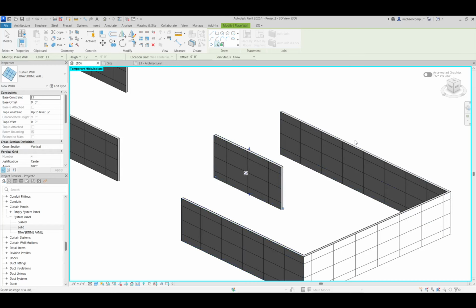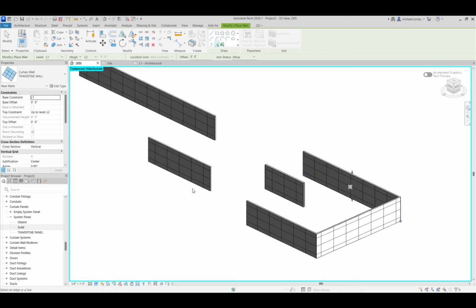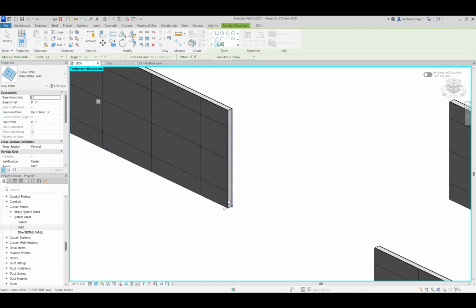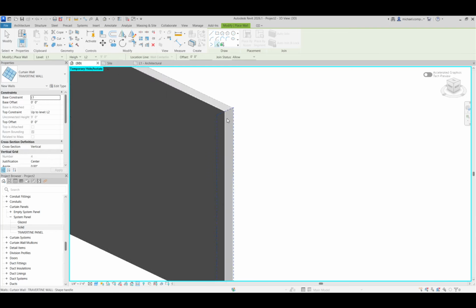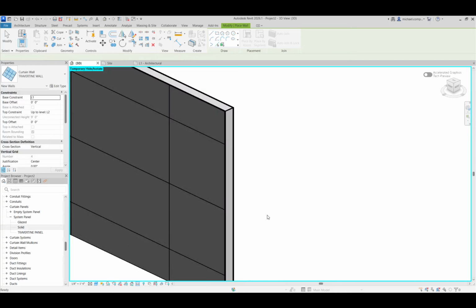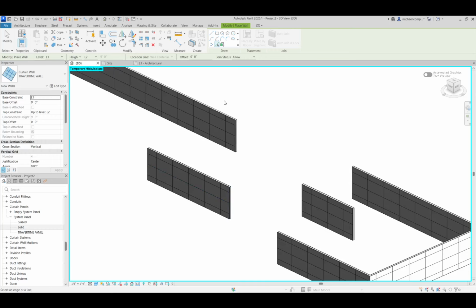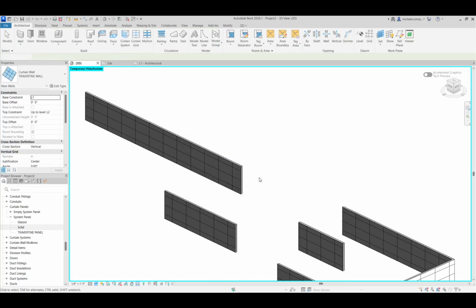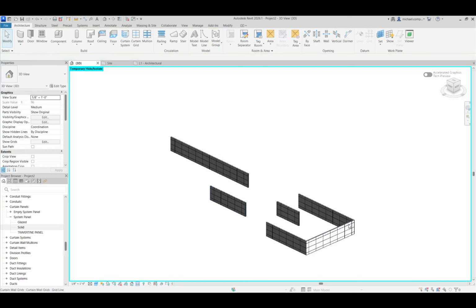And now I have to go on every wall and the ends to get this thing to show up correctly. Oh, that didn't show up correctly. So that's not good. So I guess what I'm trying to say is I think it's worth the extra step of doing the mass model and applying them using the face command versus using the wall tool and the pick.